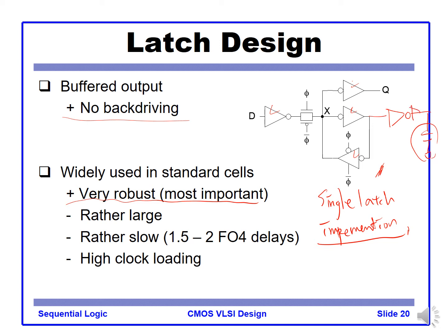Then you may have to add an additional inverter there, so that the output loading doesn't affect the latching effect, right? So this one has a high clock loading because many devices here are loaded by the clock. It is quite a slow implementation, but very robust.